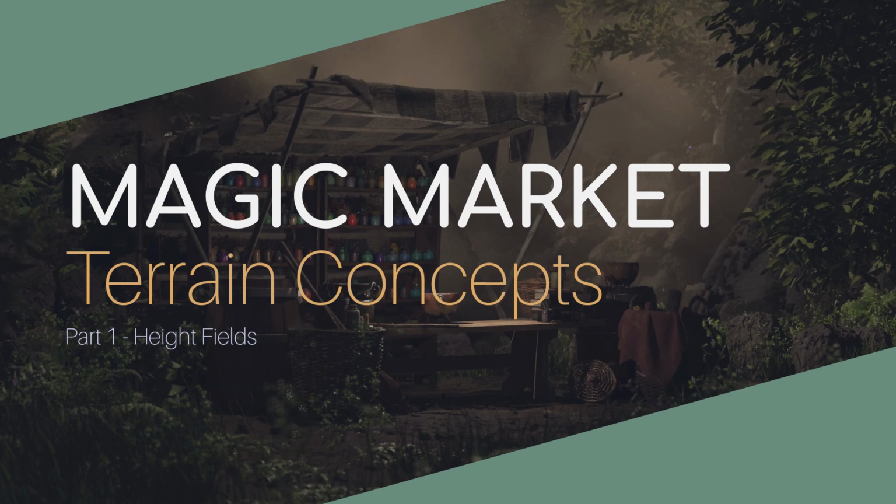This is part of the Magic Market series in which we were responsible for creating all of the environment assets. So in this tutorial we're going to be creating a terrain from scratch using Houdini. That means creating the height field and then generating various features on our terrain based on the type of terrain that we're going for. We're then going to generate masks based on those features and use them to drive our textures.